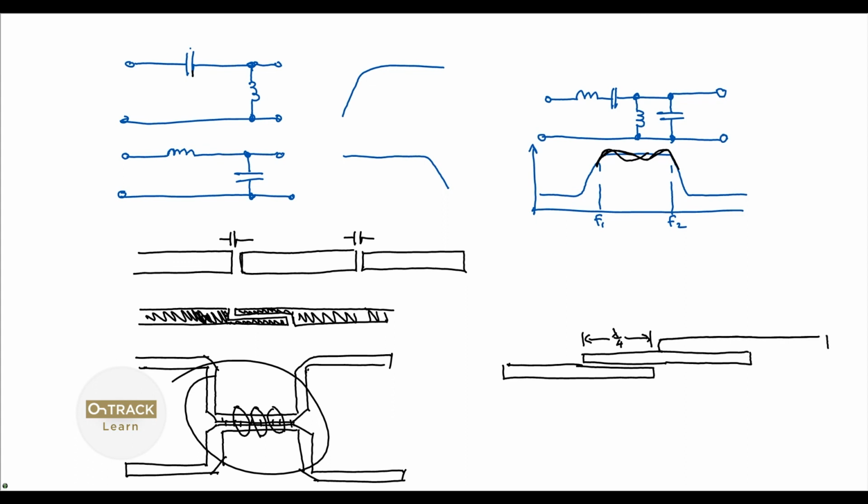We can have multiple segments overlapped, and they are couplers in between the segments, and each of these sections, typically a half wavelength long, forms a resonator, and it resonates at the center frequency that we want for our bandpass filter. And these can be made to be reasonably broad, usefully broadband devices as well. So let's go to a new page and look at one of those.